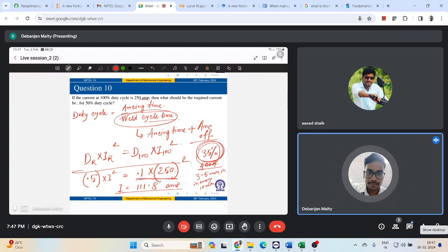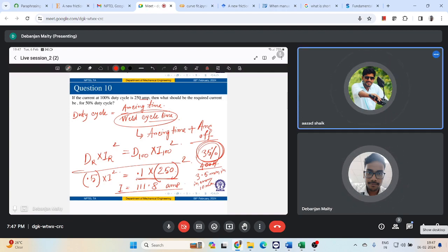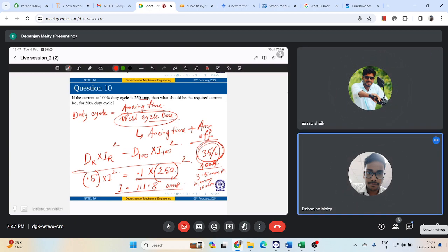In each and every industry, whoever does this fusion welding, in terms of arc welding, you have to have some knowledge of these power sources: what kind of voltage-current relationship it follows, what the different components of your power source are, like sir was talking about the rectifier, inverter, to create the required amount of voltage and current.